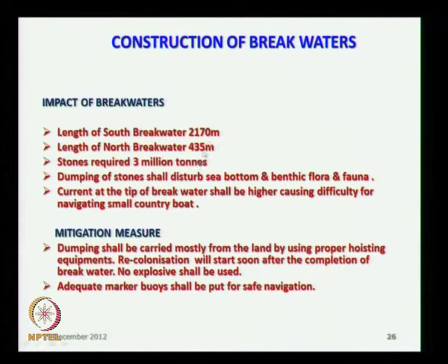So when you want to construct the breakwater, the southern breakwater is about 2 km and the north breakwater is about 500 meters. The stones required are about 3 million tons with artificial armor. Now it has gone up to about 6 million tons with a berm breakwater. When you dump the stones, they will disturb the sea bottom and benthic flora and fauna. Current at the tip of the breakwater shall be higher, causing difficulty for navigating small country boats. These are all the impacts.